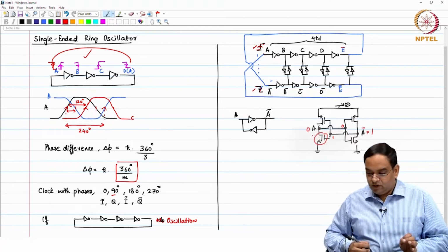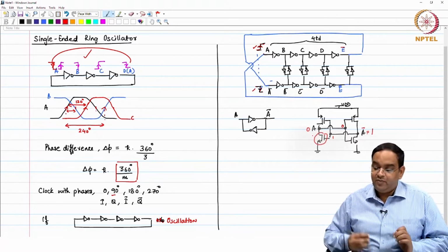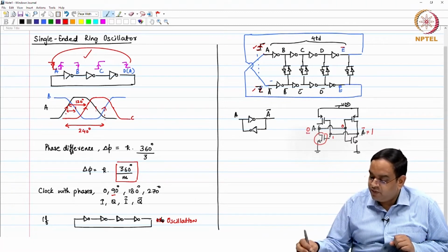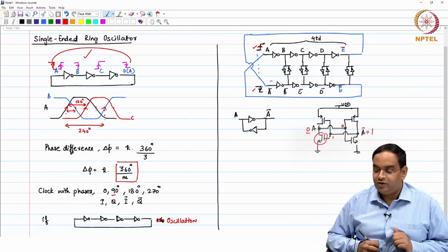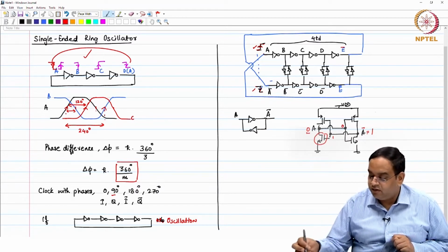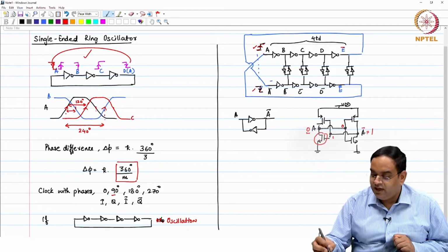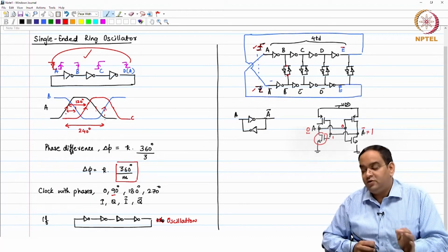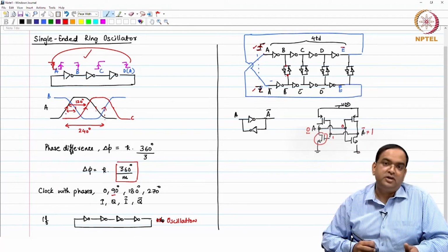So, this cross coupled latch actually maintains the inverted relationship between its two outputs. Okay. So, it has the two outputs which you are looking at, they are these nodes. So, if you have one on one side, then the other node will become 0, okay, and it will enforce that relationship.